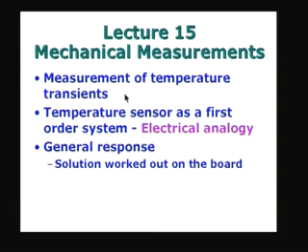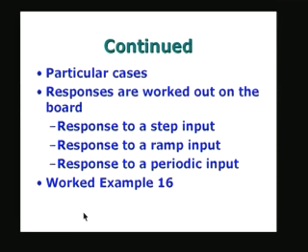What we will be doing in this lecture is to look at a temperature sensor and describe it mathematically in terms of a first order system behavior, and we will also draw an analogy with electrical circuit theory, and we will look at the similarities between the two systems. We will look at the governing equation, we will derive it and then work out what we call the general response for any variation of the temperature, and after doing that I am going to take 3 particular cases.